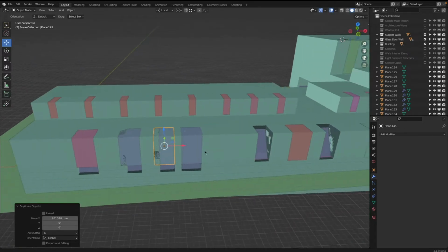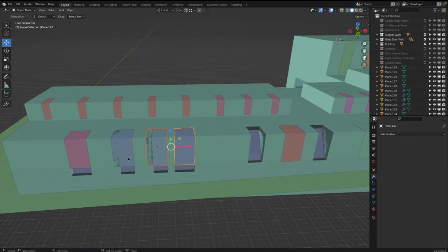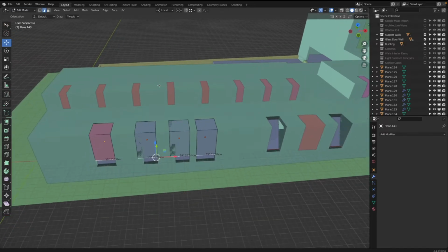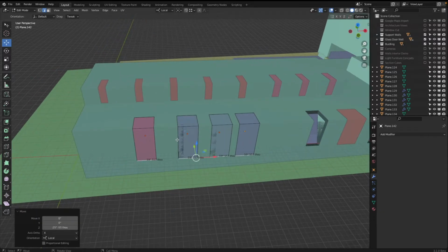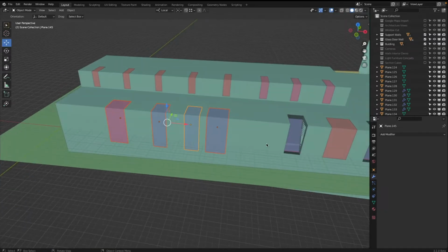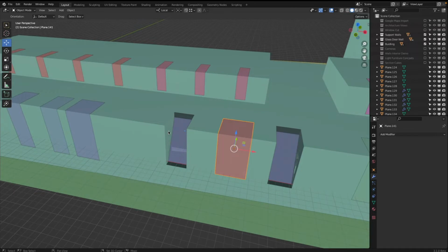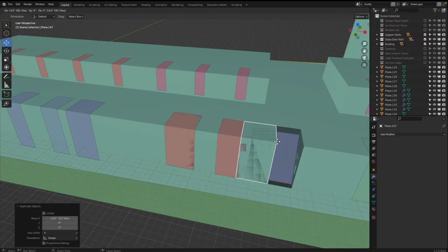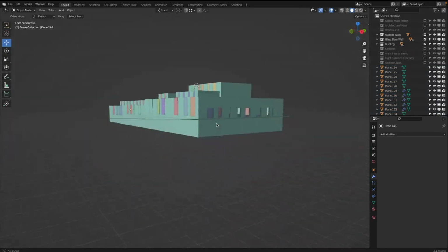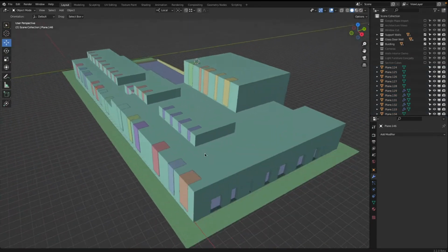Shift D there. So you see they're not at the right height. What's really nice in Blender is you can select multiple objects, and then when you go into edit mode, you can select multiple geometries at the same time. So you don't have to go into edit mode, leave edit mode. It would be great if SketchUp could do this more. Shift D, go to there, Shift D, go to there, edit mode for both, zack, and there I'm with Control Snap, finish this. Yeah, now there we have this super easy.